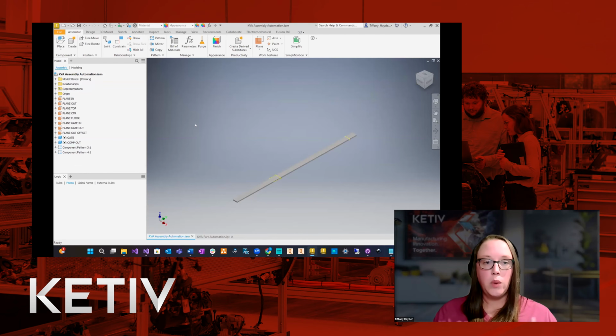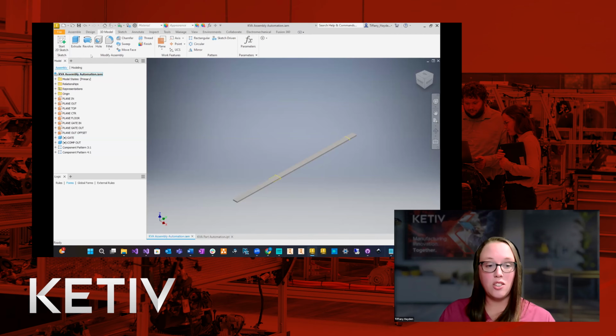A lot of times when you're dealing with manufacturing, in many businesses I've dealt with, you're still ordering a full length component, but you may need to show it in a different way. And to do that on an assembly level, to keep the bill of material the same, you want the component to not be edited at the part level, but you can actually cut away material from the assembly level. And we tend to do that with assembly cut extrusions. To do that, we need to create a sketch.